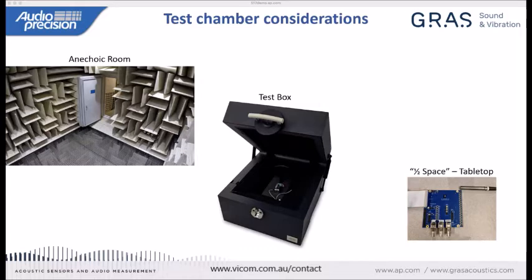I think what's probably understood by most of you is that the physically bigger the anechoic chamber, the lower the lowest frequency at which it doesn't have any internal reflections. So a test box can be a good solution because we can have a relatively small test box if, say, we're only interested in frequencies above 400 hertz. There's a direct relationship there.